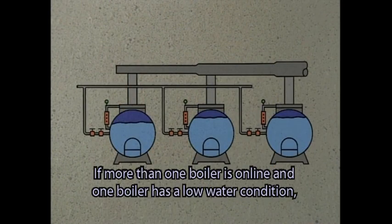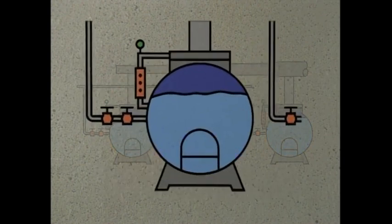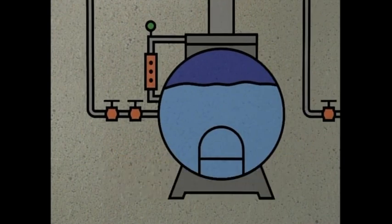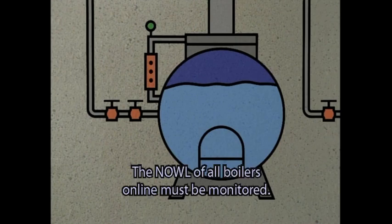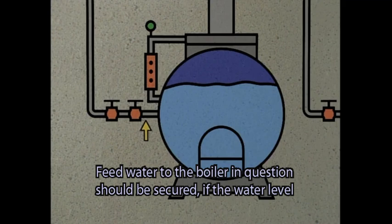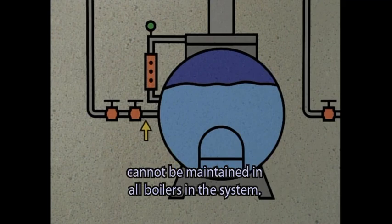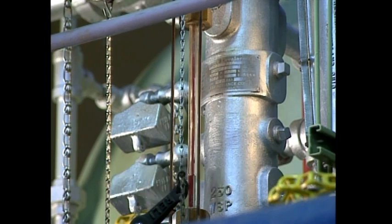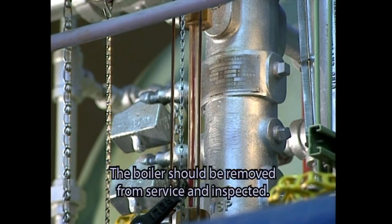If more than one boiler is online and one boiler has a low water condition, the fuel to the burner of the boiler with low water must be secured. The NOWL of all boilers online must be monitored. Feed water to the boiler in question should be secured if the water level cannot be maintained in all boilers in the system. Whenever a low water condition occurs, the cause must be determined. The boiler should be removed from service and inspected.